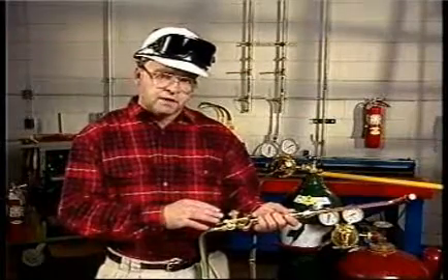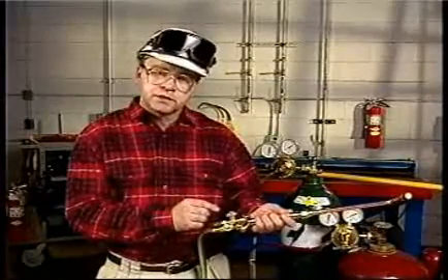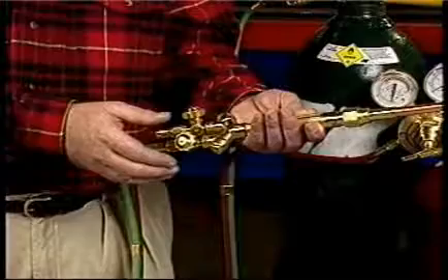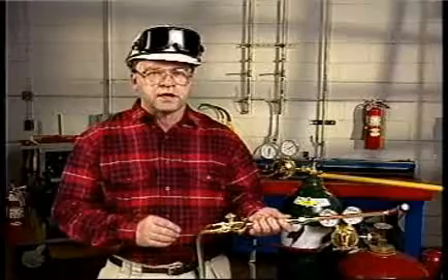The fuel gas valve is then opened, the gas ignited, and the flame adjusted. Then the oxygen valve is opened and the flame readjusted until the desired flame configuration is achieved. When you use the proper equipment and follow correct procedures, the oxy-fuel process can be accomplished safely. However, it is necessary to be aware of potential hazards, which, if ignored, can result in serious injury to the operator and damage to the equipment.